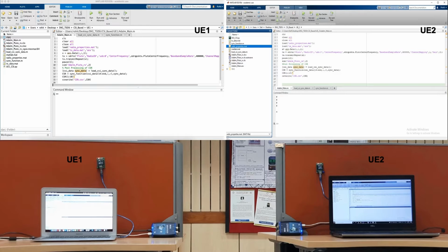Now we will demonstrate dynamic key generation on soft channel, which we will obtain by using ADALM-Pluto, our software-defined radio platform. ADALM-Pluto by Analog Devices offers a wide range of full duplex tuning from 325 MHz to 3.8 GHz, with a sampling rate of up to 61 megasamples per second, hence offering an instantaneous bandwidth of 20 MHz.